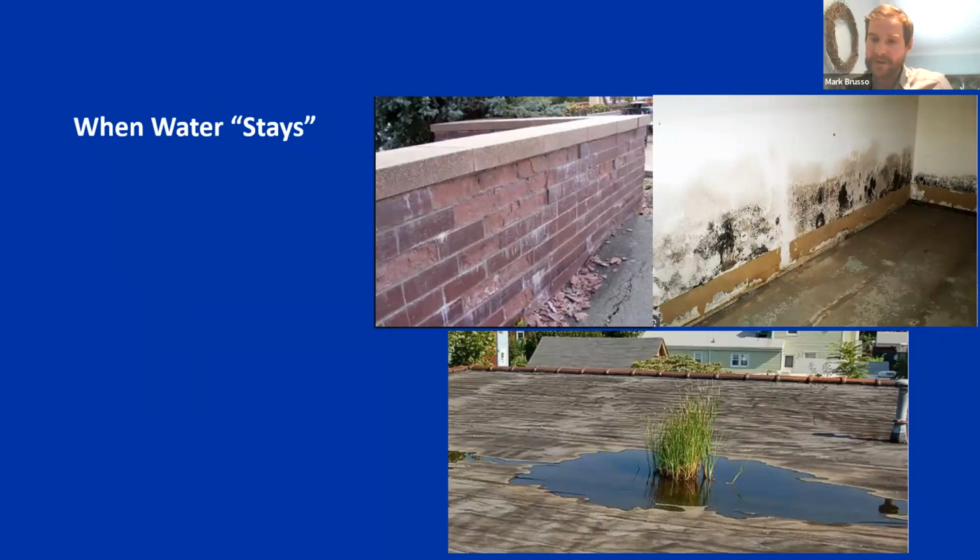And then importantly, I like to look at roof systems, specifically flat roofs, because positive drainage is also important on so-called flat roofs. If water ponds and stays there, it has an opportunity to create an oxidative environment where the roof breaks down a lot quicker than if we had a positive roof slope in that environment. So again, anytime water stays present on these building materials, it accelerates deterioration very quickly.